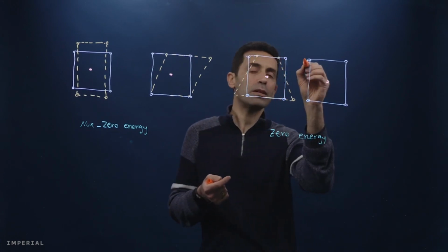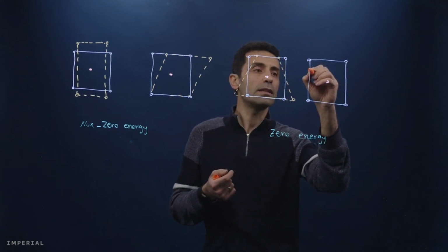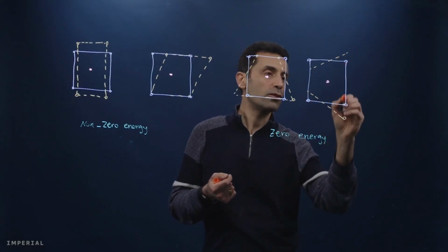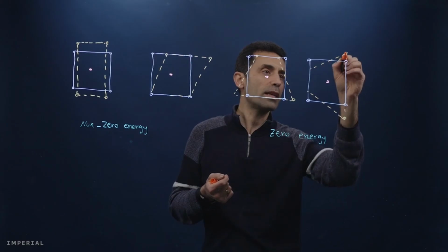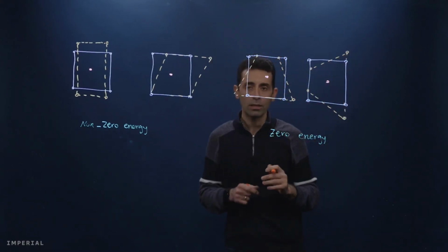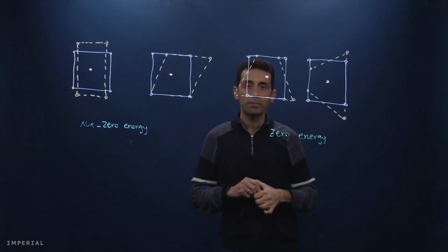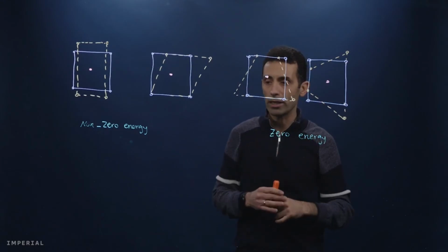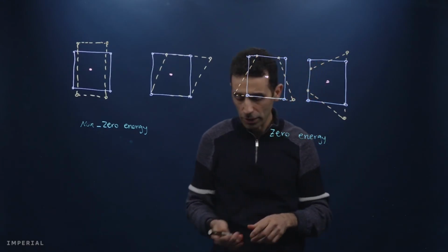It can be the other way around. So it can be like this edge. So the vertical edges, this one is extending and this one is contracting. And again, if you use a single integration scheme, then this does not really feel these kinds of deformations. We call them the zero energy deformation.